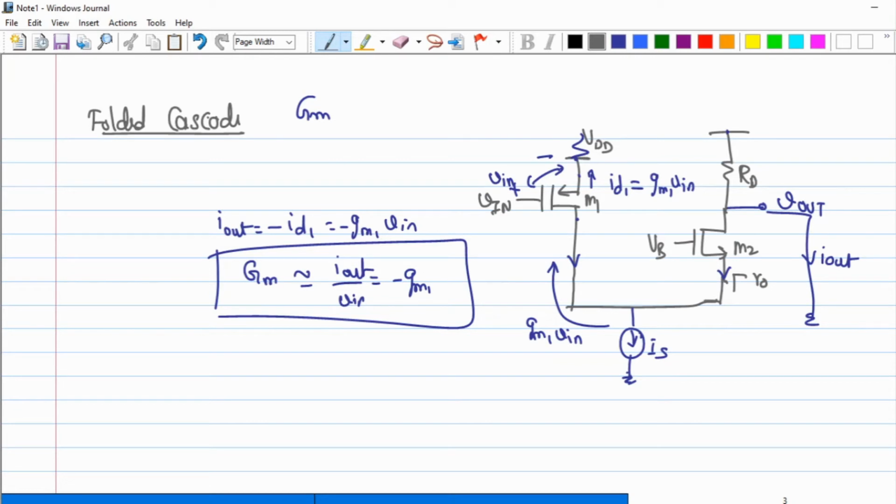But can I bring the value of VB down? Yes. Why? Because as I reduce the value of VB, I'm trying to push the source node towards the ground. Now when I do so, the drain of this M1 is going towards a lower potential. Will my transistor stay in the saturation regime when I try to do so? Why does the source potential have to go down when I vary the gate potential? Think about the source follower. What is the literal meaning of source follower?